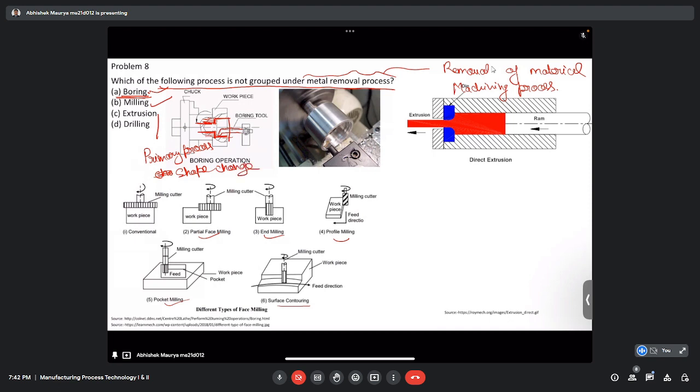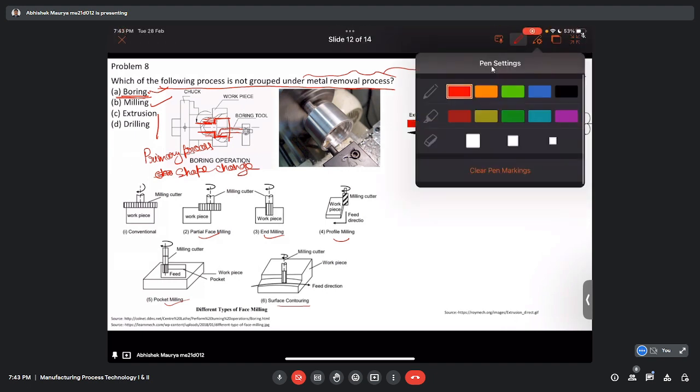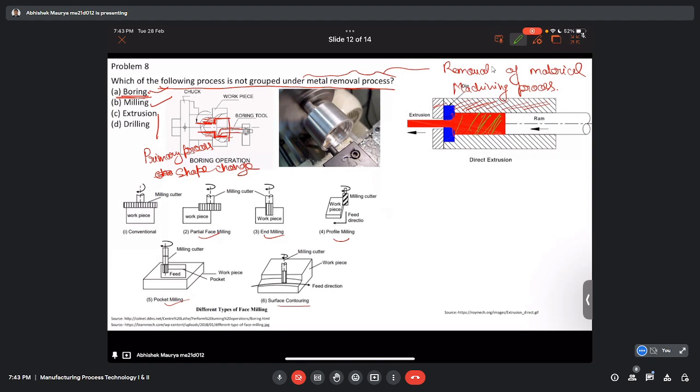So extrusion is the process to get a component which has uniform cross sections, like tubes, bars, or I sections. The process is very easy. We have some die, and inside the die we are putting some billet. It is shown already in the red. So this is the billet, and we are trying to push the billet through the required cross sectional geometry.